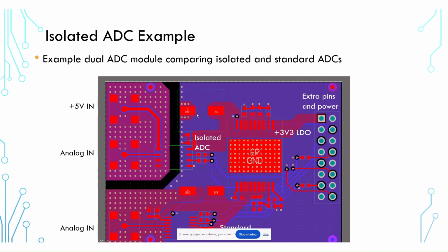And then you can see here that there's nothing being routed between the two sides of this system, okay? So if you did have separate grounds, as we have here, with the purpose of maintaining galvanic isolation, once again, you do not want to route between these two sections.